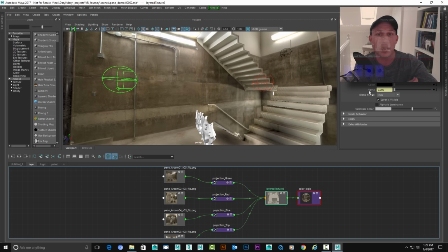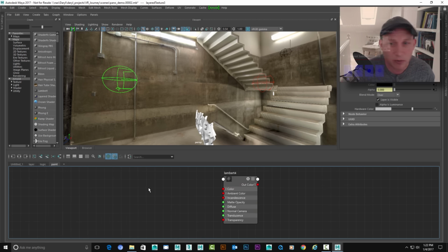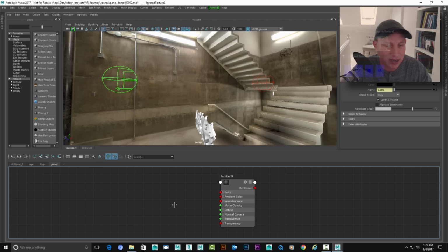So how do you handle making those alpha channels? Well, I like to use texture maps to do that. And I actually like to paint a red, green, and blue file because that gives me the ability to get pure masks, 3 different masks as well as a 4th mask where there would be no color. And it gives me one easy mechanism to generate where these textures are going to be applied. So how do you do that?